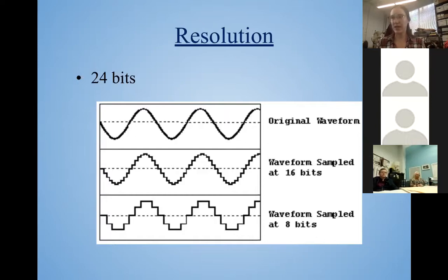Both of the resolution aspects, this slide and the previous one, these are the best practices, as I mentioned, for high quality resolution. The more you crank these up, the higher the resolution and the higher the audio file size. So 96 kilohertz, 24 bits is pretty large of a file for audio. What you're going to get typically on your compact disc is 44.1 kilohertz and 16 bits, if I remember. I'm pretty sure I committed that to memory. So CD is kind of like the minimum for digital audio that our ears are happy with.